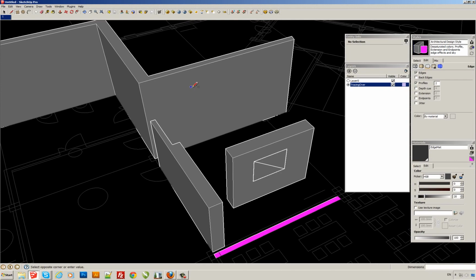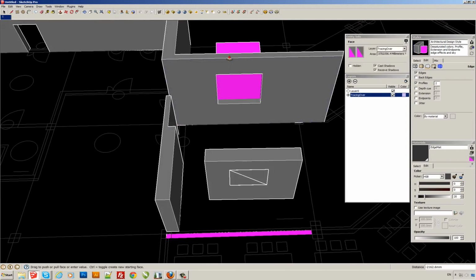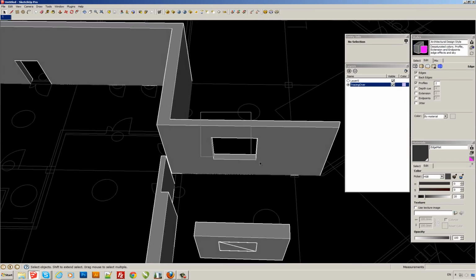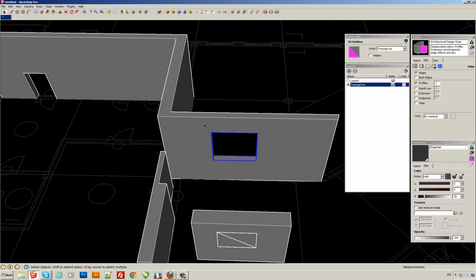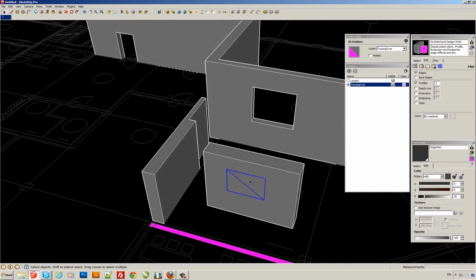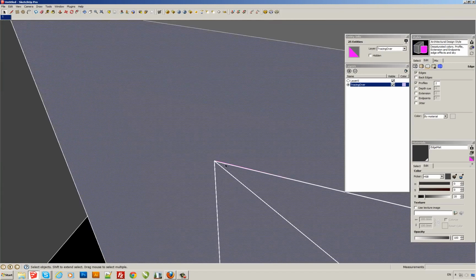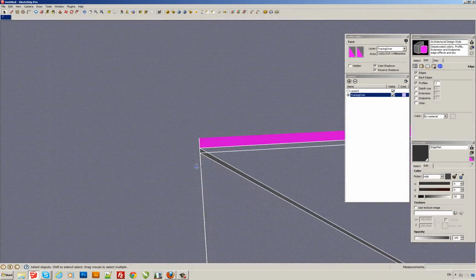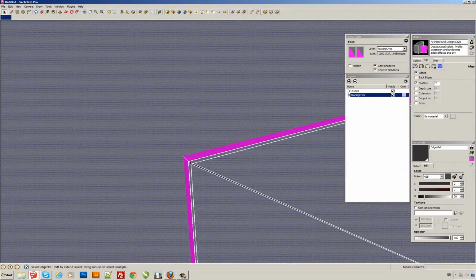When you are creating windows right, just select all the geometry involved in the window, and in the entity info you should see the 16 entities, not more. If you will see something like 25, it tells you about the problems which can bring you the headache in the further modeling and further exporting.